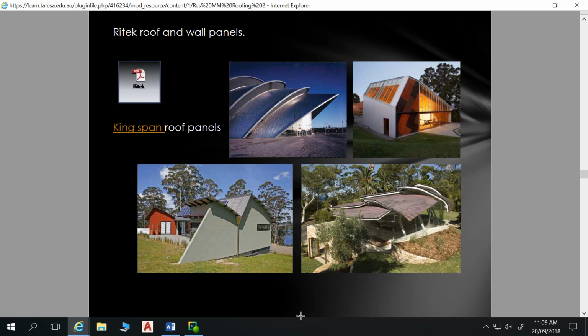For example, if we've got a wall, we've got our stud walls and we've got our insulation in between all the studs. Where our studs are, that piece of wall is not insulated at all, and you've got these materials that connect together, and heat gets transferred in and out. Still, the way that it's assessed is that portion that has the insulation is assessed. So that's for that wall they'll get R 2.5 or so.